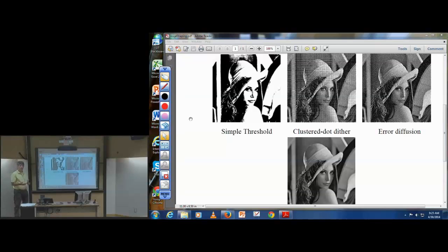So for example, if I have a micromirror device for handheld, that mirror either reflects light or not, and each micromirror is tuned to a particular color. So it tells me whether or not I'm going to have color at a certain pixel on my screen. And then the pixels on your micromirror device are chosen to be smaller than you can see. And so what your eyes will do is aggregate enough of these micropixels to make one pixel you can see, which combines all the colors, which are all binarized, around it in, say, a 3x3 grid, in which your eyes actually see the average color in that pixel, which is now made of 3x3 or more of these subpixels or micropixels.